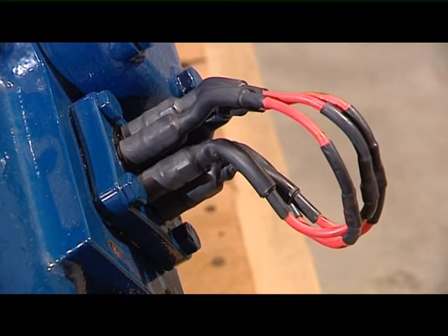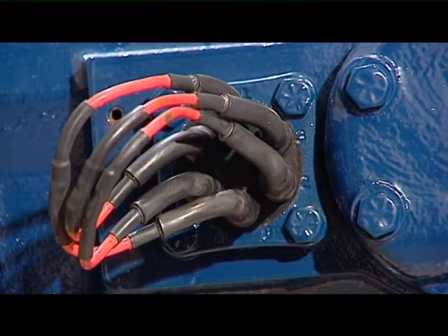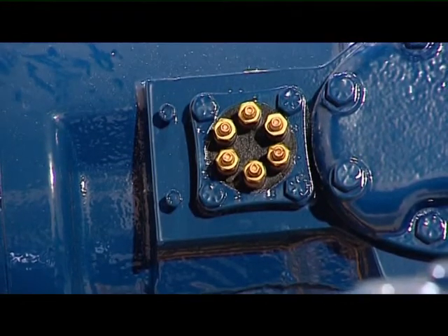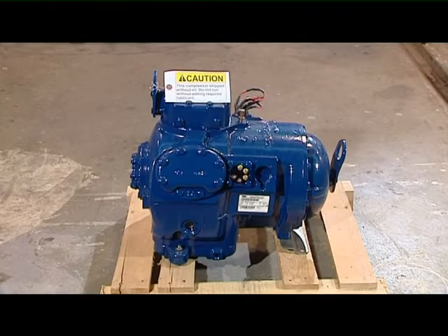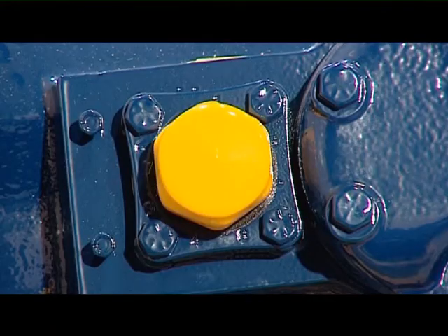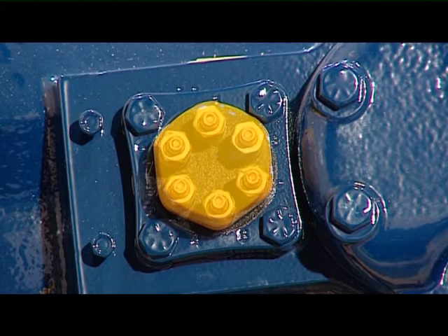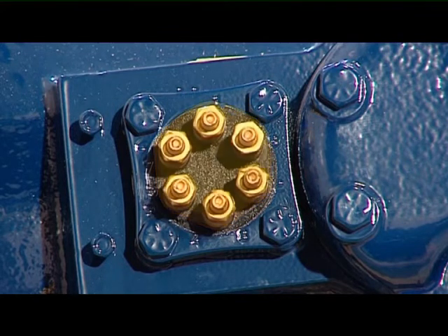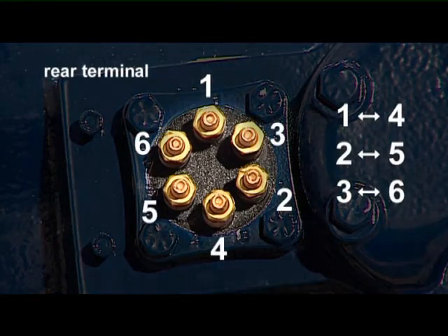for a mono-voltage compressor. If it's needed as a replacement of a dual voltage compressor, just remove the bridge connection from the rear terminal. If the spare compressor on board has been supplied without a bridge and it's needed as a replacement for a mono voltage compressor, you will have to bridge the rear terminal as follows: 1 to 4, 2 to 5, 3 to 6.